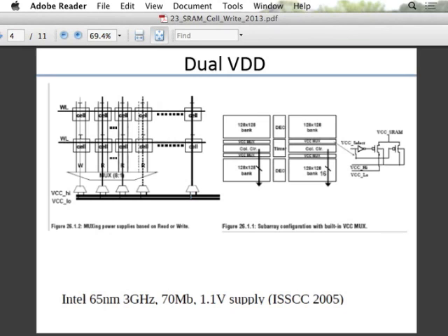And this has a benefit: tomorrow, if you want to increase the number of columns, for this whole column you have one module. As a module you have done the layout, you have figured out the right sizing, you just stamp one more and you are done. Otherwise, it becomes messy. Question? Yeah.